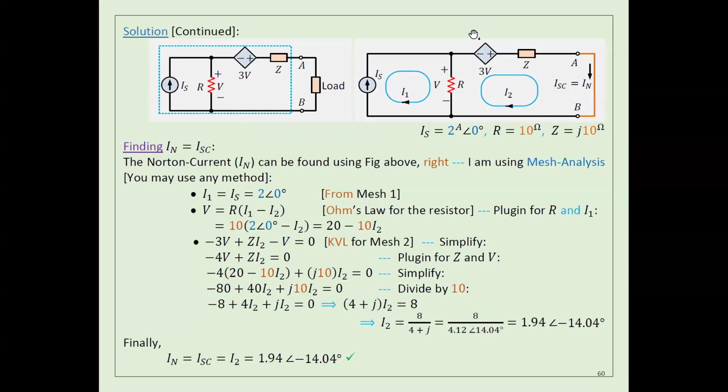So anyway, I will explain it, look here, guys. What is the voltage here? The voltage here is V, right? So I have only one unknown, which is V. So you can apply Kirchhoff's current law. Here's the input current IS, which I already know. The current IS should equal the current here, which is V divided by R.